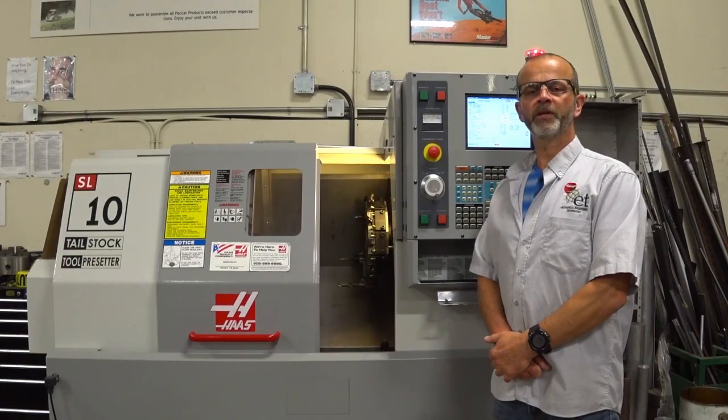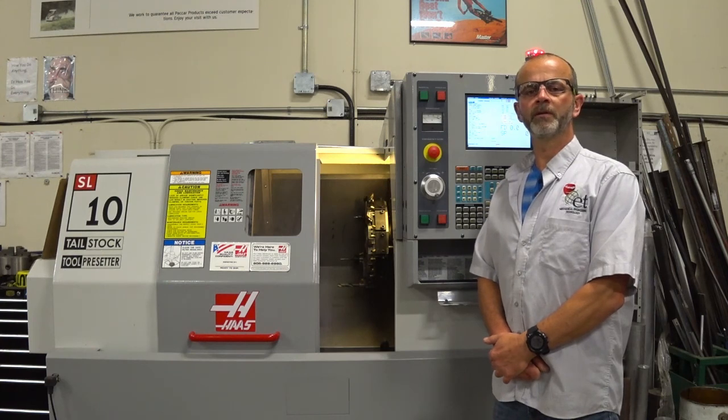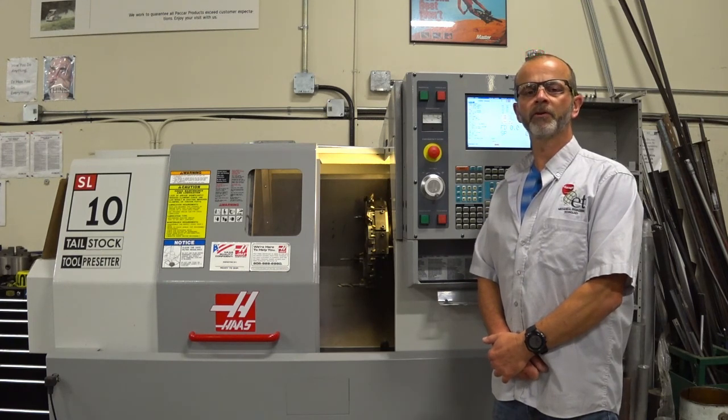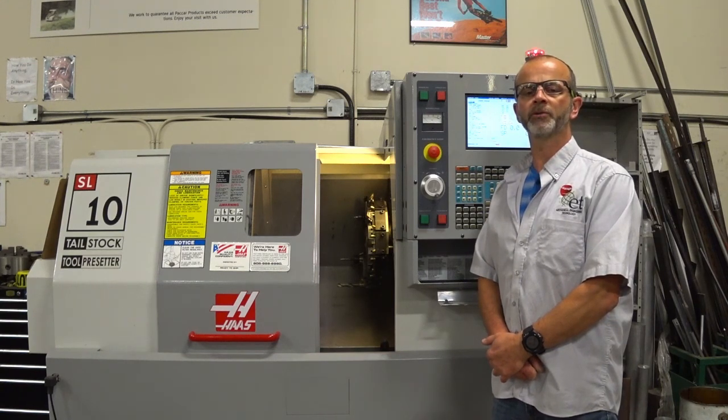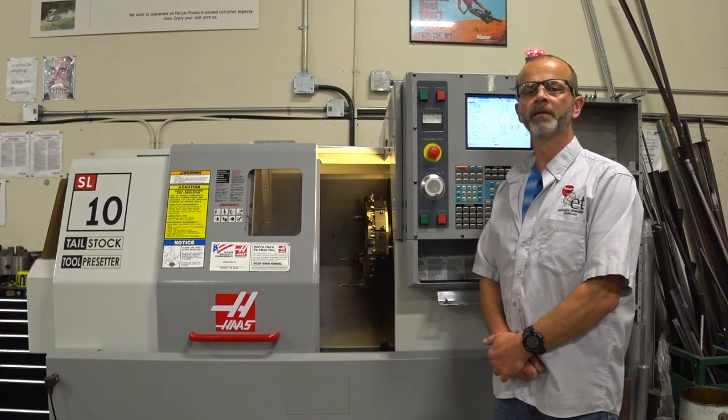Okay, so that video hopefully identified a few unique G code and how they're used in the CNC lathe, specifically the importance of the G50 line and how important it is to have that to ensure your spindle does not overrun, causing material to be ejected forcibly into the cabinet.